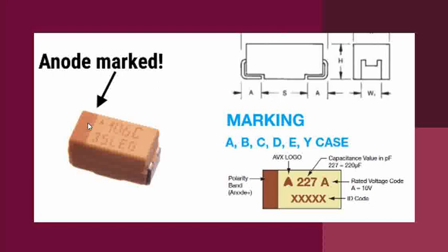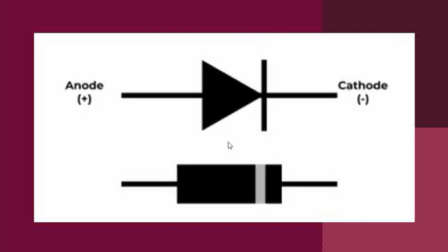This is clumsy, right? If you have a diode and a tantalum capacitor nearby, most engineers do get confused instantly when they look at it. They might know, but they just want to double check that they are reading it correctly. So for the tantalum capacitor, remember that the marking is the anode, whereas in the diode we have seen that it is towards the cathode.